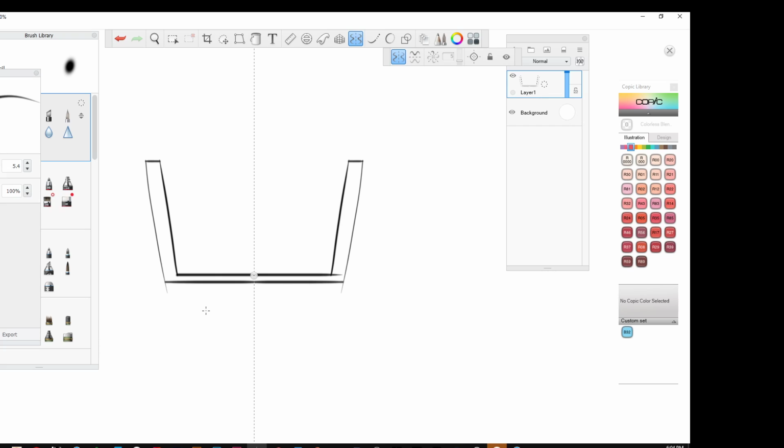So, do you know why? Like, do you know what you need to take into consideration and why you have to have draft? I think for the rotational molding portion, you don't want to have sharp edges, so something to make it easier to create the form. So it won't get stuck in the mold. So that's not really radius related, but right, you don't want it to get stuck in the mold.